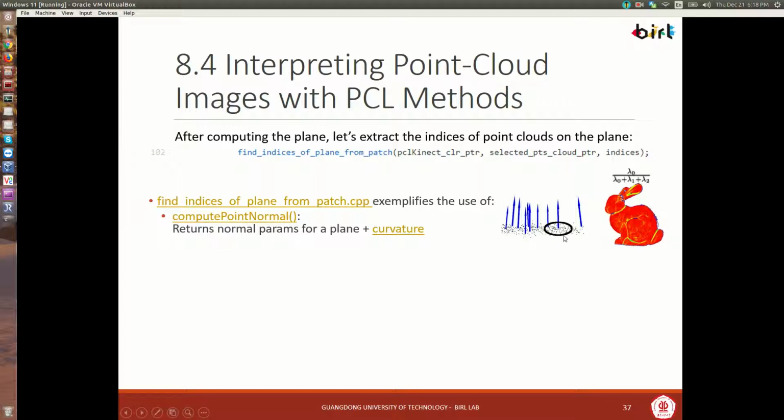You can look at the tutorial here, but basically by selecting the nearest k neighbors, we can get an idea of the normal plane for those points. The parameter k is important because if it's too small, we might get some noise or some disturbance here and not get the true normal. For curvature, we're using eigenvalues, where lambda 0 is less than lambda 1 is less than lambda 2, and this gives us a sense of curvature. And you can see here that wherever we have a yellow line, we have high levels of curvature.